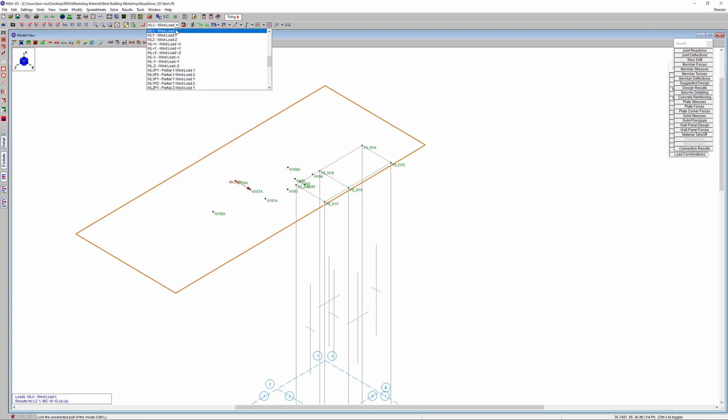Our wind load, our transient loads are going to be calculated here. So we're going to get our transient load. So let's go ahead and look at, here we go. Our transient loads are calculated now based on that. So we can see here that this is basic load case 8. So this is the transient load that's coming from basic load case 8. So basic load case 8 is our wind load in the X direction. And this is that distribution like we saw in our PowerPoint presentation.